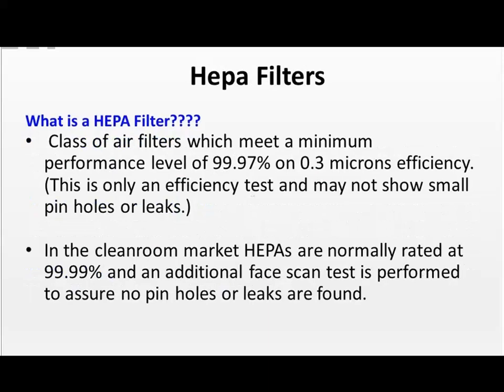Now, the FDA standard 209E is not used as much anymore as the ISO standard. But again, these are similar. The ISO standard may be just a little bit stricter, and we're going to look at those. But they're both looking at classifying your manufacturing rooms based on the particulate 0.5 micron in size that are being detected or being filtered out per cubic meter or per cubic foot.